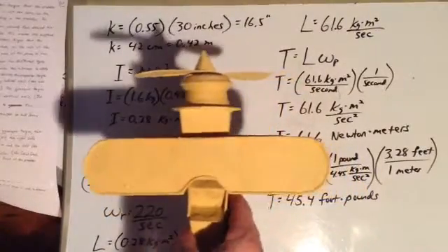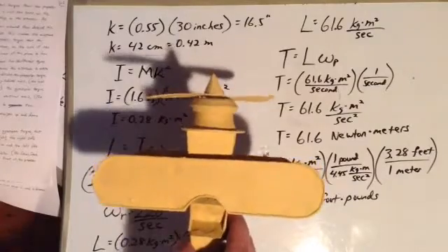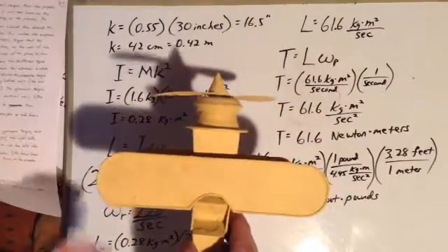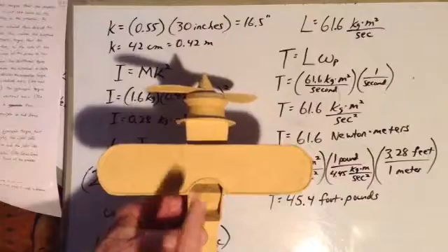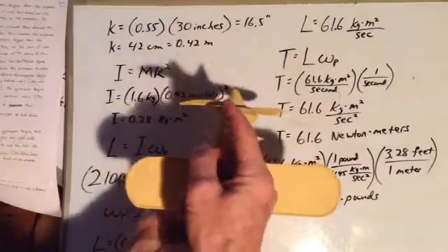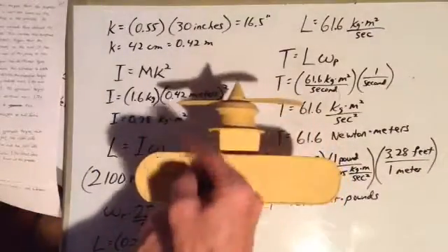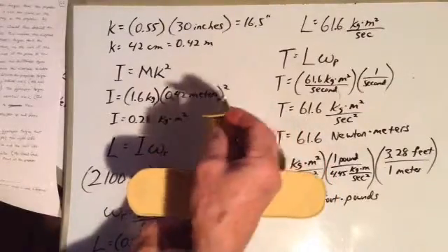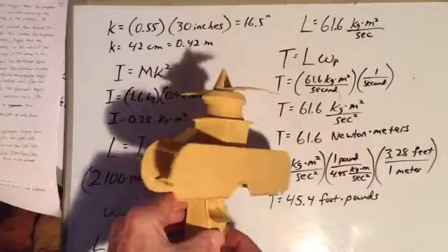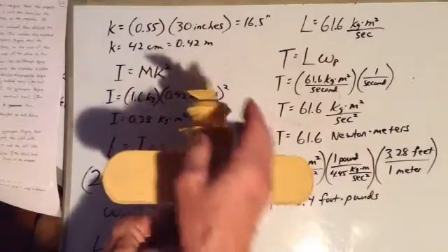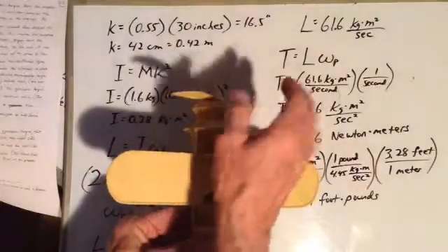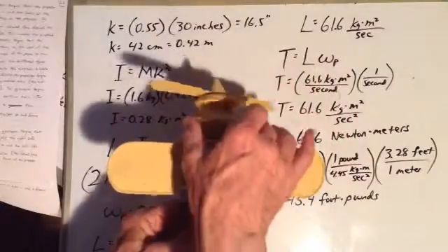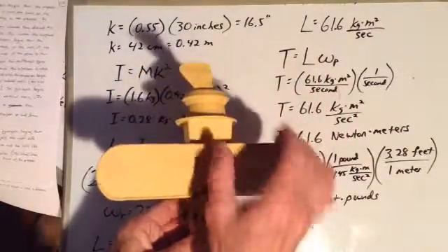This little airplane can illustrate what we're talking about. The propeller of the steel stork, as viewed from behind the airplane, if you're looking this way, spins counterclockwise, so going around like that. Okay, this makes the airplane tend to roll clockwise, because anytime your engine is turning this thing that way, the engine wants to turn the rest of the airplane that way.